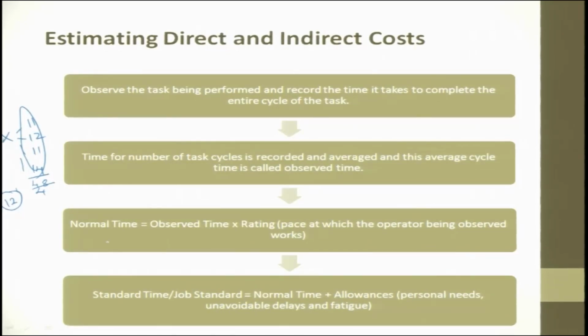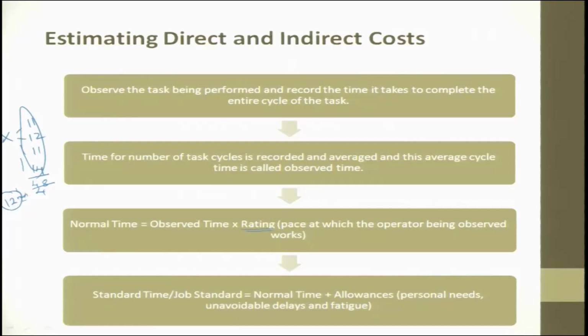So what is the normal time? Normal time is nothing but observed time into rating. I do not take 12 minutes all the time, because if I do, then we do not give any fatigue allowance, and we do not give an allowance for him to attend to his nature's call. If you do not give relaxation, that might lead to fatigue and tiredness, and he does not perform very well, or there is a possibility mistakes can happen.